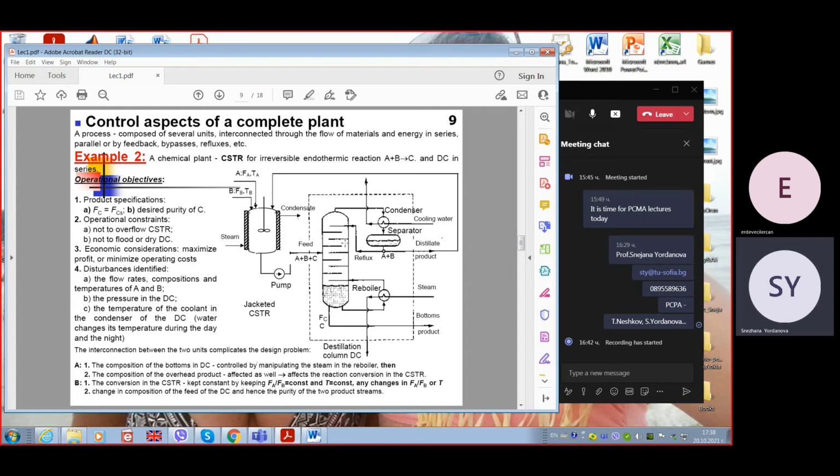So for the upper boundary, the top product, gaseous, is condensed and separated in these two additional installations. The condenser is cooling these vapors to obtain liquid A and B. And part of this liquid A and B is returned to make the upper boundary, to cool this part in case some C is taken by the energy of the gas.